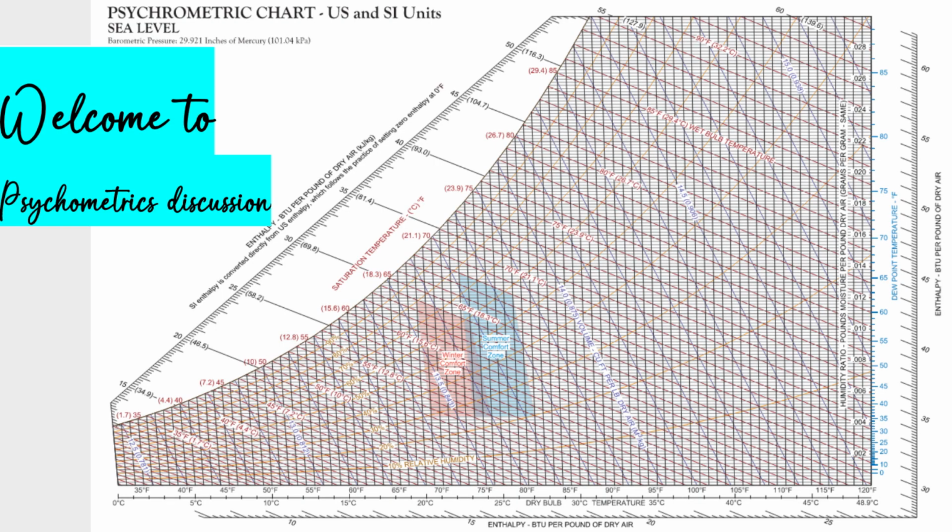Today we're diving into psychrometrics, the science that explains how air and moisture interact in every HVAC system. Psychrometrics is the study of the thermodynamic properties of moist air and the processes that change those properties. It's the foundation for understanding air conditioning, dehumidification, humidification, and all HVAC processes involving air moisture. Every HVAC system manipulates air properties. The psychrometric chart is your roadmap showing exactly what happens during heating, cooling, humidification, and dehumidification processes.